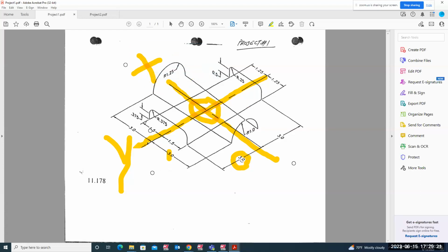So now I'm going to go to construction plane front and I'm going to create this rectangle right here. And then we're going to make radiuses over here. But we have to control our Z. How far is my Z over here? Like I said, that Z is right here, 3 inches. Then I'm going to create this rectangle here back from origin going back Z minus 3 inches. That's right here. So let's go to construction plane front and change my Z to positive 3 inches.